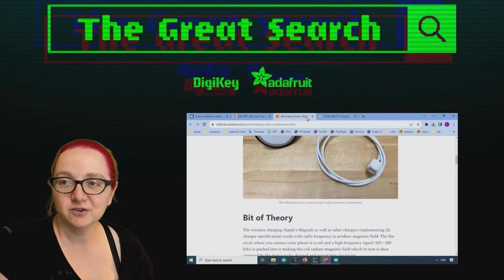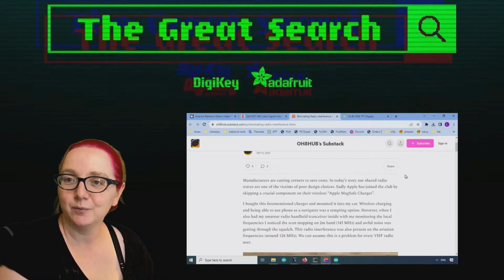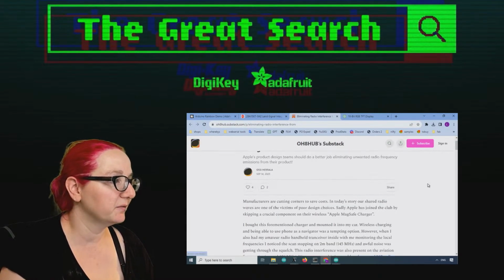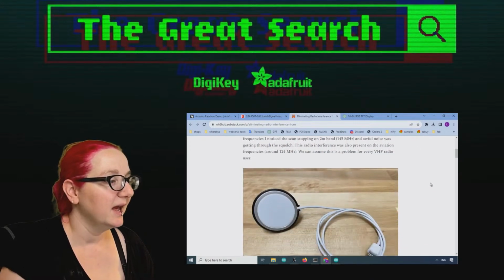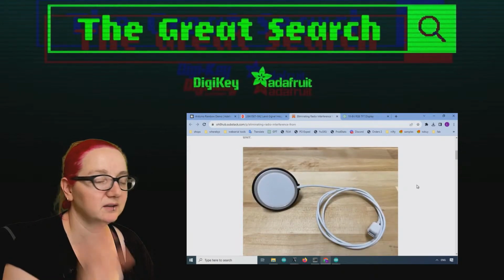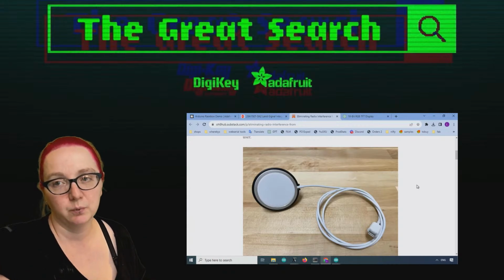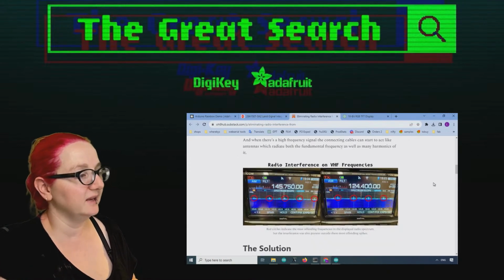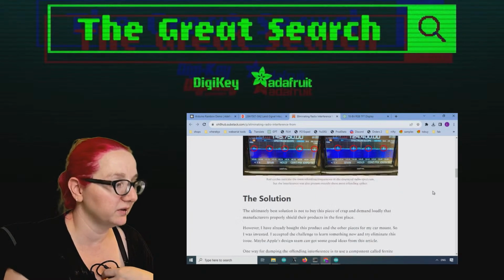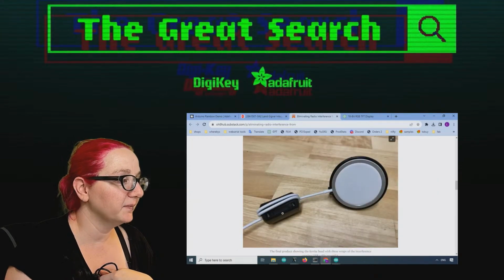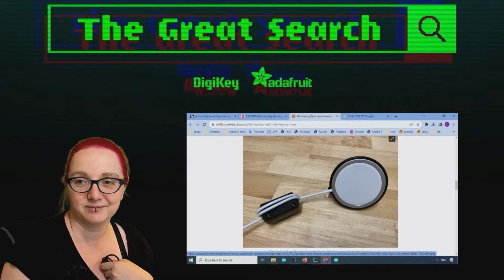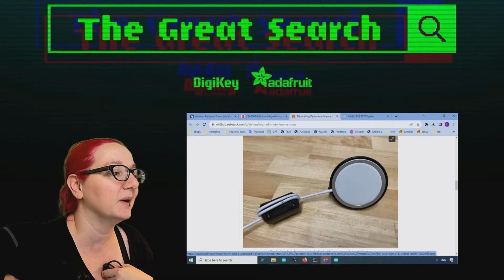Okay, so sometimes I just look online and I'm like, hey, what? I read the blogs and stuff, and I saw this post from a couple weeks ago, from OH8 Hubs. They were using one of those Qi chargers or a mag charger with their phone, an Apple device. And they were doing VHF work, and they were noticing that there was some radio interference on VHF. And they showed, if you ever have a device like this, the whole thing is an EMI machine, it manufactures EMI.